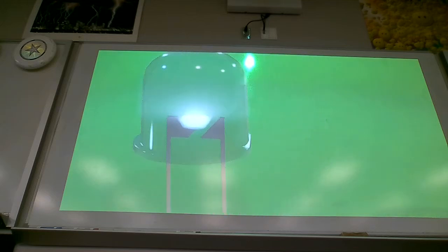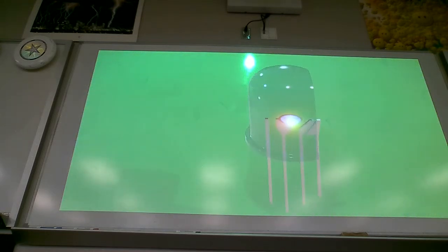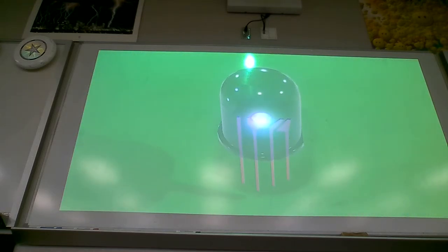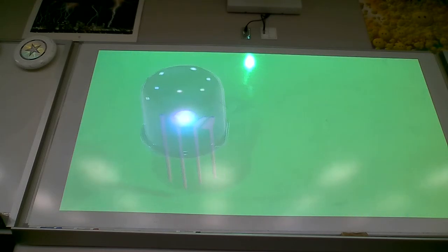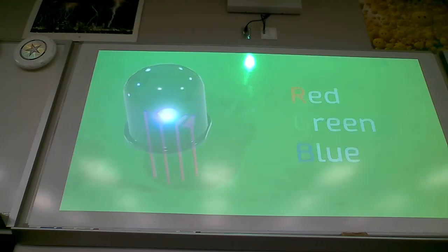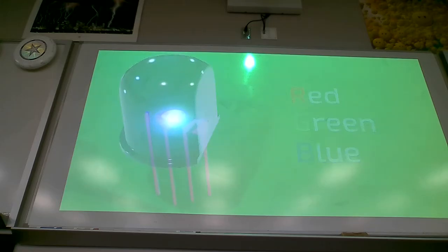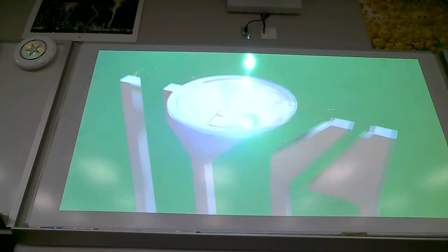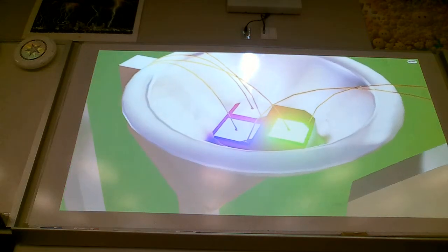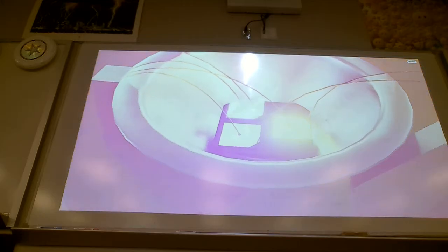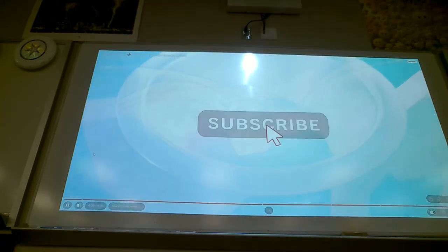The last thing I want to talk about is RGB diodes that can produce multiple colors. Although the truth is there is not much mystery left to it. The RGB name refers to the colors that compose it: red, green, and blue. Well, indeed, within this type of LEDs there are 3 pairs of semiconductors specifically selected to produce each color, and by independently varying the voltage that passes through each of them, the perception of different colors is generated.